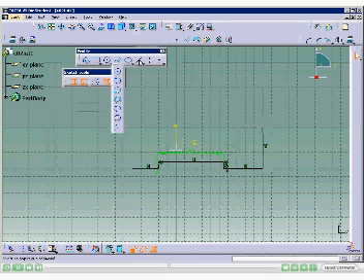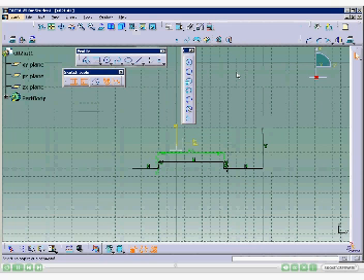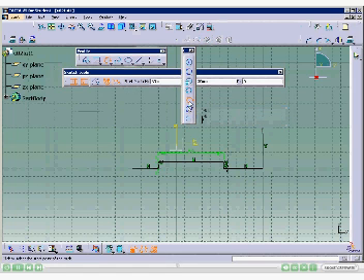This draws the third vertical line of length 50 mm. Next, you will draw an arc. To draw the arc, first invoke the Circle toolbar by choosing the down arrow on the right of the Circle button in the Profile toolbar. Choose the 3-point arc button to invoke the 3-point arc tool. Dock this toolbar from the drawing area by double-clicking on the toolbar.